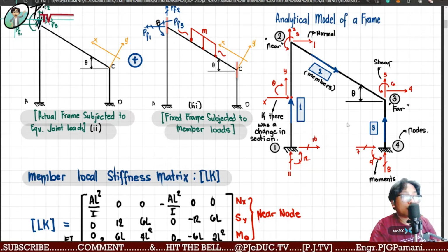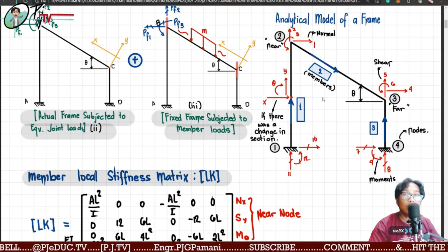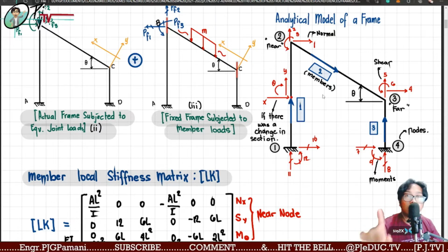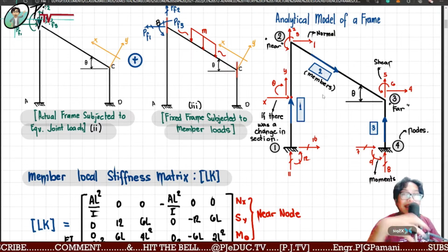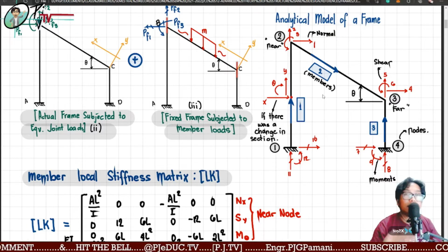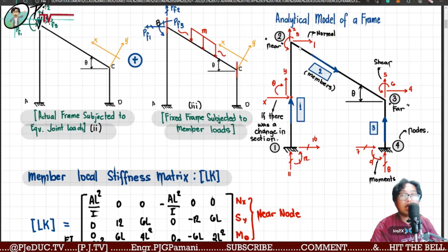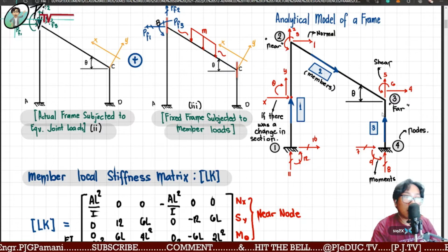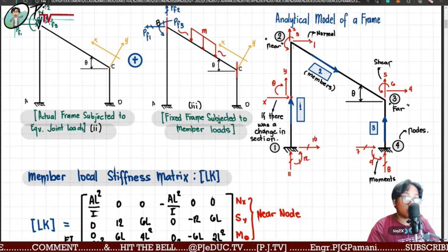Okay? As I've already said kanina, start placing your axis forces and bending moment on joints which has known or identifiable joint loads. So probably at node 2, node 3, there are applied loads there. And probably there will be unknown deflections at those joints.